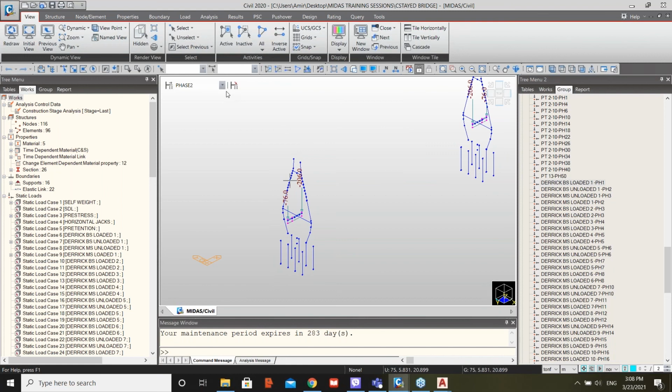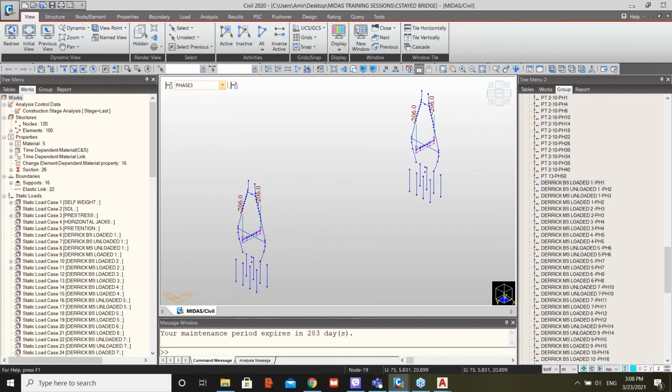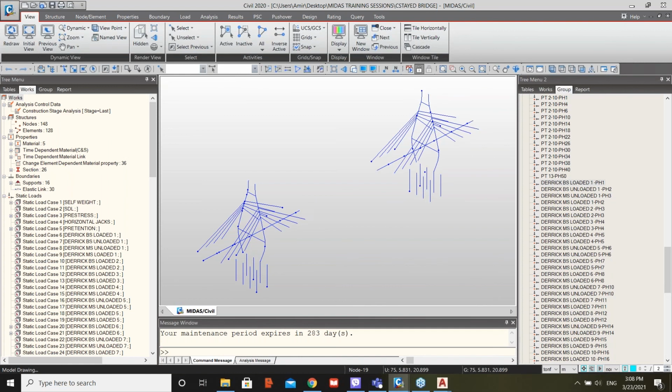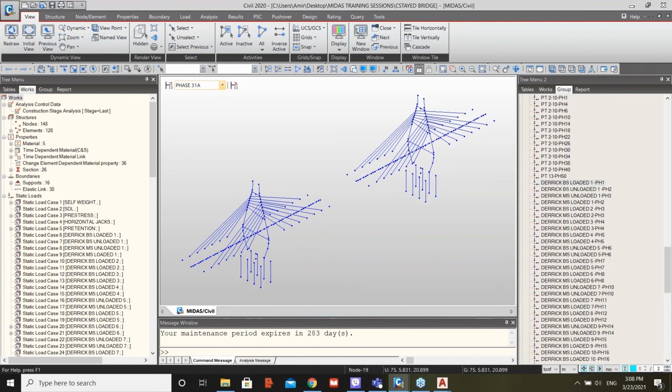So that's how it's tensioned, which means that each cable is tensioned in a different phase. So that is how you progress, and in one stage you put the stays on and pre-tension them and proceed until all the phases are completed to the middle of the bridge, where you cast your last segment, which is the closure segment in the middle.